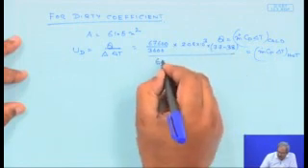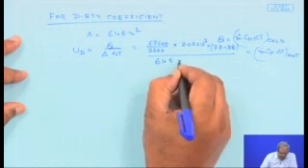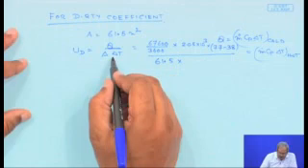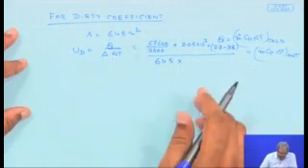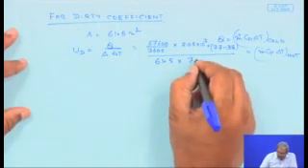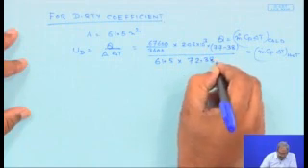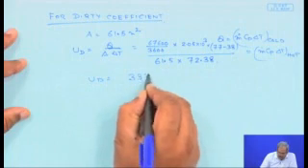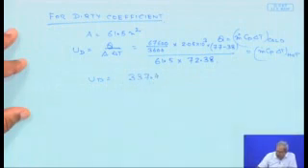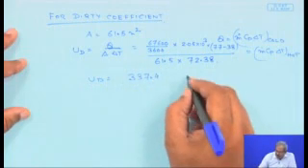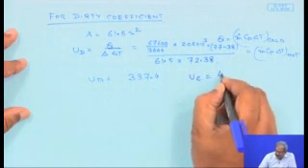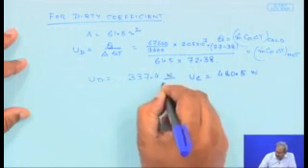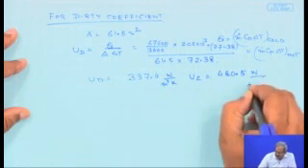The area is 61.5, and the delta T, this is the corrected value of the log mean temperature difference, which we have calculated to be 72.38, and therefore UD is 337.4. So from our previous calculation, we have found UC to be equal to 480.5 watt per meter square Kelvin.